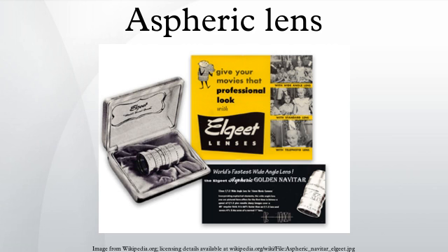They can be made by point contact contouring to roughly the right form, which is then polished to its final shape. In other designs, such as the Schmidt systems, the aspheric corrector plate can be made by using a vacuum to distort an optically parallel plate into a curve, which is then polished flat on one side. Aspheric surfaces can also be made by polishing with a small tool with a compliant surface that conforms to the optic, although precise control of the surface form and quality is difficult, and the results may change as the tool